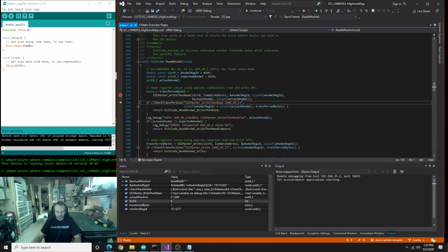And the reason we transferred it was because somebody, basically this address here, is now on the bus that acknowledged it. So when it saw that address, we sent back an ACK instead of the NACK. So negative acknowledgement didn't happen. We did a positive acknowledgement, pulled that wire low. And then we read back a value, which it read as a 0. So the actual value is 0.